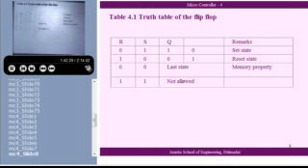Same way, if I take R as 1 and S as 0, the other way around, Q is 0, Q bar is 1. This is called a set state. When Q is 1, the flip-flop is said to be in the set state. When Q is 0 and Q bar is 1, it is said to be in the reset state.